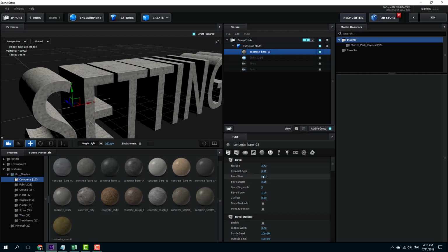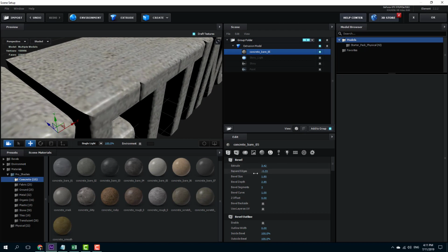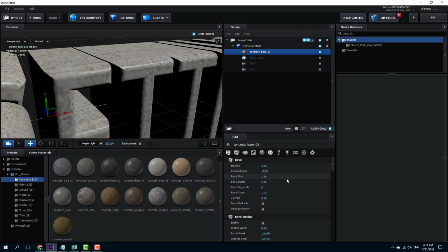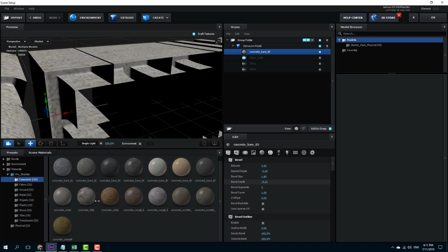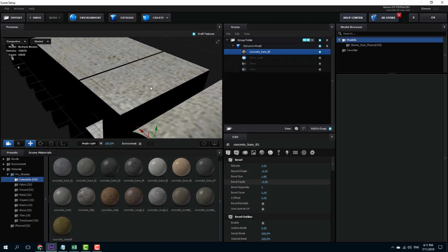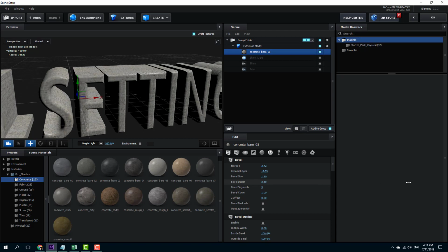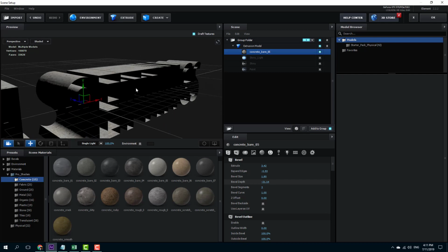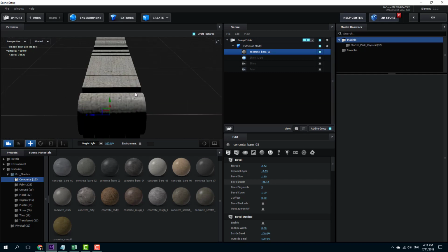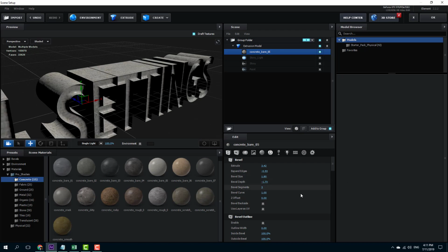So that's the bevel size as well. If you increase the bevel size, you can see that it bulges more. You can decrease the bevel size just like that. You can also decrease the depth to create a negative bevel effect, as you can see. Now every text actually goes inside, and it creates a very unique effect. You can bring it forward to have a smoother look or bring it inside just like that. All right, so now there's a negative level of bevel. You can just expand this out and then it comes forward again.